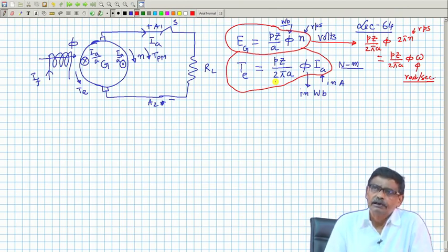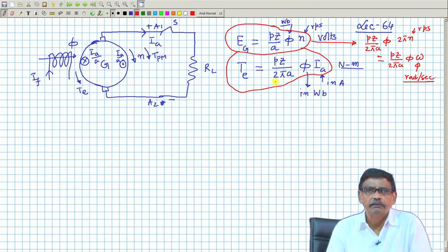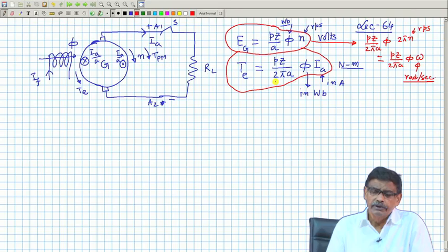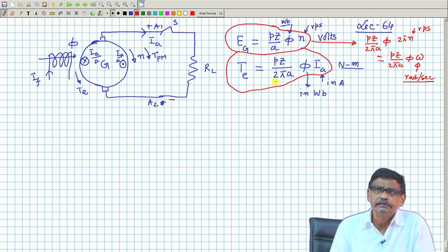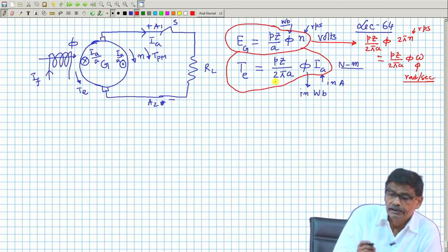In any rotating machines, I have been telling you through my Machine 2 course that to produce torque in a DC machine, the number of stator poles and the number of rotor poles must be the same. And another thing I told you is that the field produced by the stator and the field produced by the rotor, the angle between them should be time invariant, should be constant, then only it can produce sustained electromagnetic torque. Now, in the case of a DC machine also this is true. Why? Let us see that.